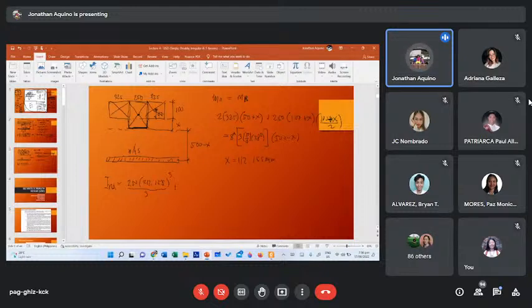So the moment of inertia at the centroid plus transfer moment of inertia. So the moment of inertia about the centroid is 325 BH cubed, okay, 100 cube over 12. Kasi dun tayo sa, ang reference natin dun sa centroid. Plus, okay, transfer formula for moment of inertia plus AD squared. So the area is 325 times 100, times d squared. So d squared, okay, center of this is 50 plus x, which is equal to